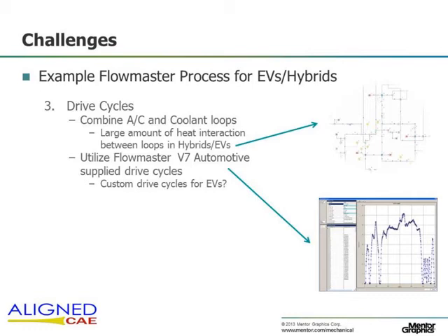The other thing we try and take into consideration is the thermal mass of the components as well. The motors and inverters themselves actually have quite a bit of thermal mass. So what we see is often a lot of heat soaking and thermal lag as the system gets up to temperature. That's all taken into consideration during the transient simulation. In a steady state simulation, those thermal masses don't have any effect because it's just a single point in time.